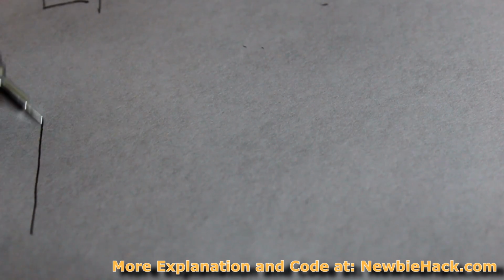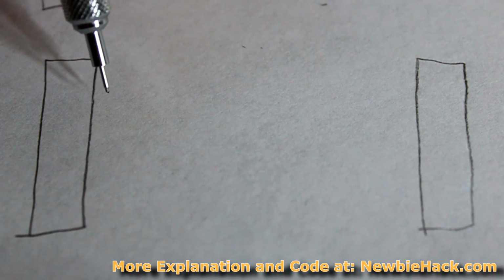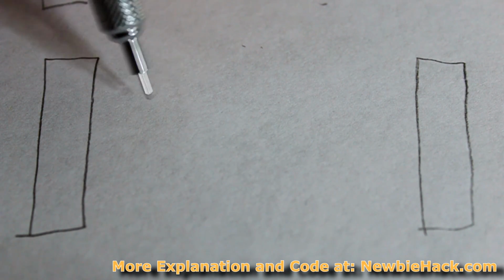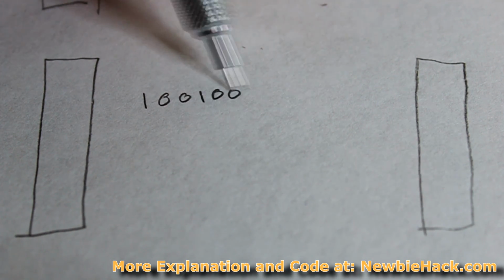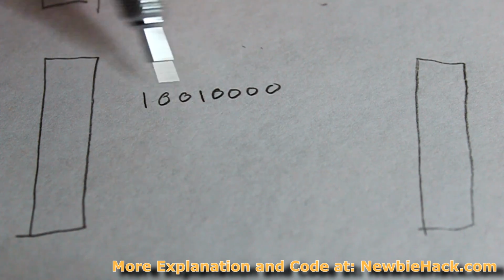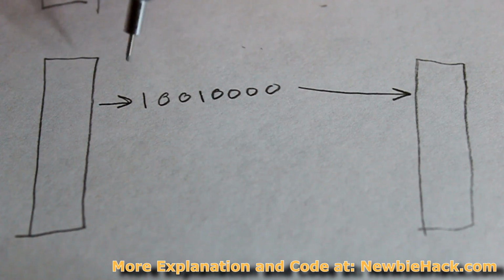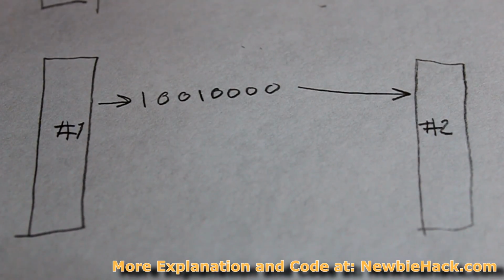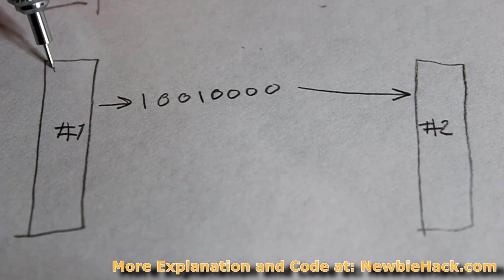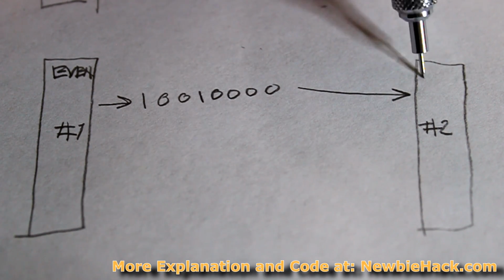Let's draw a couple microcontrollers. If we wanted to send over, let's say, 8 bits, I'm going to do a couple ones and zeros here. This would be my transmission data bits from this microcontroller to this microcontroller. This is what I want to send from number 1 to number 2. So let's say we set the parity to even on both sides. I'm going to set you to even, and I'm going to set you over here to even as well.